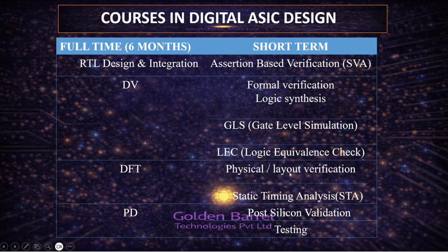And physical or layout verification. Then static timing analysis, STA. Post-silicon validation and testing. As of now we have SVA, formal verification, logic synthesis, STA, LEC, layout verification, post-silicon validation and testing.